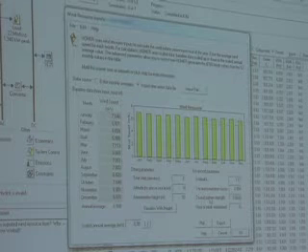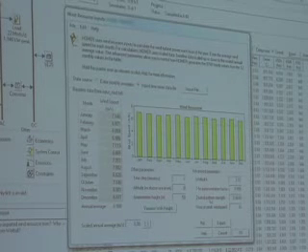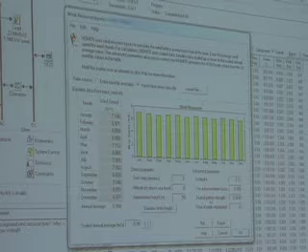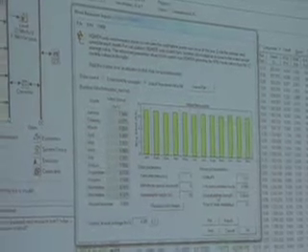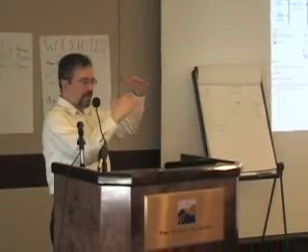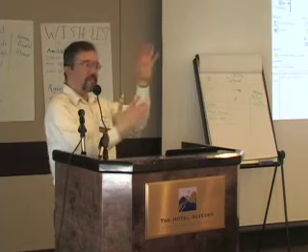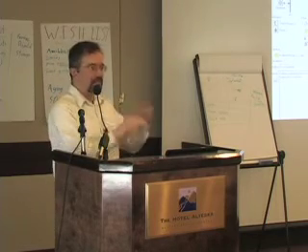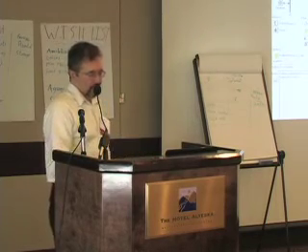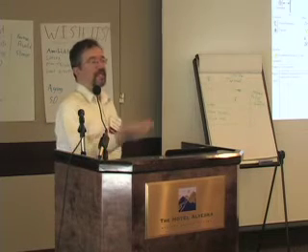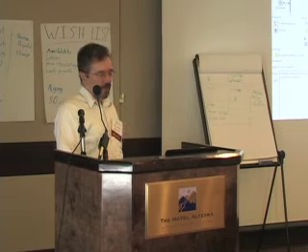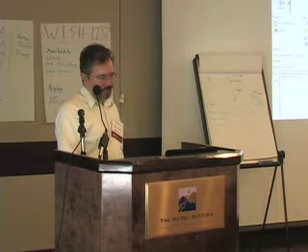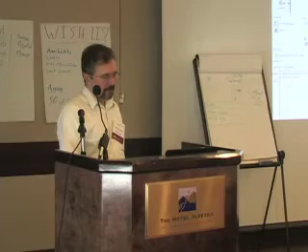So what Homer does is it tries to fit a sine wave with a 1 day period to the data, and the strength is the amplitude of that sine wave, and the hour of peak wind speed is just the point where it's at its highest point. So you import data, Homer calculates these parameters for you. If you don't have data to import, let me start fresh here.